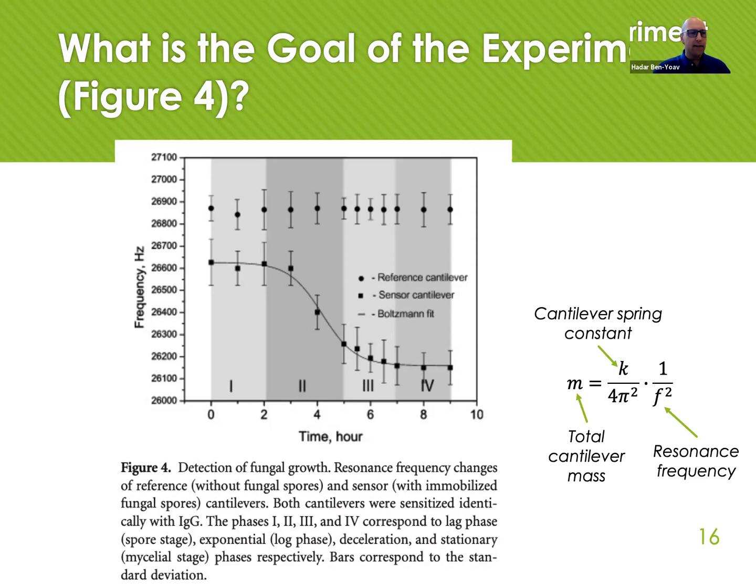So very nicely, these guys developed a sensor that can detect spores only by the change of the frequency, or by the mechanical change of the cantilever. And they can continuously monitor. It's semi-continuous, meaning that you put the spores and the nutrients in the cantilever, leave it like this, and measure every half an hour. So they could use the same sensor repeatedly, measuring the resonance or the amount of spores for different time periods.